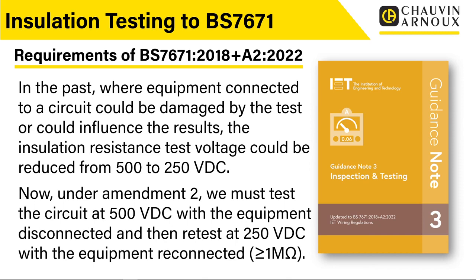It almost makes the test impossible to carry out, or certainly very difficult to carry out. So I think there will be arguments that people will use in this when it comes down to electrical installation condition reports, and there may be limitations, or comments that people make on the test to actually say that they weren't able to carry out that test with all the equipment disconnected first.